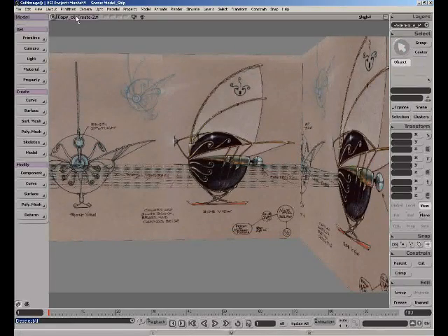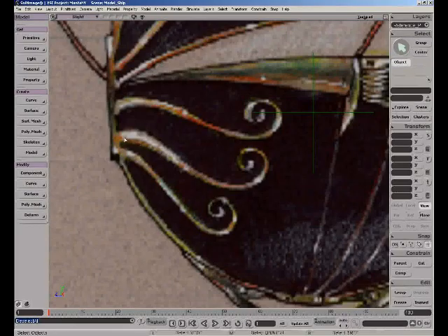So let's go ahead and take a look at the right viewport, and you can see here what I've done is zoomed in on just the area that we're going to be focusing on. So I'm going to draw a brand new NURBS curve, and just go ahead and trace the outline of this. It doesn't have to be exact, but we'll get it pretty close in there. Of course, we can move these points later if we want to, but this should do for now. And we're going to go ahead and extrude that.